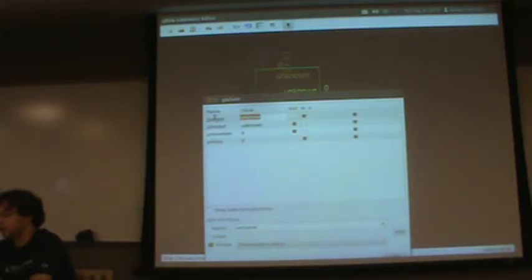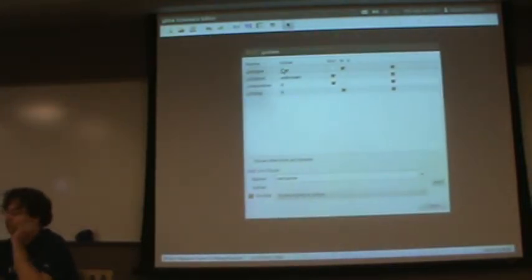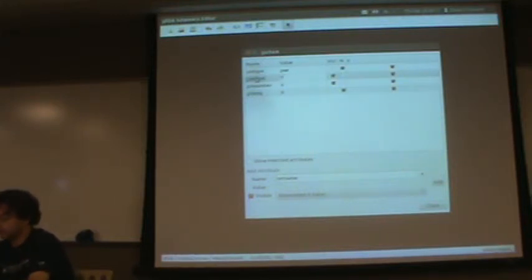So this is our power pin up top here. The pin type is going to be, I think it's called POW, no, it's PWR. There's a list of these, and I've got a link on my last slide of the acceptable names for pin types. The label, they call it VDD, so we're going to call it VDD.